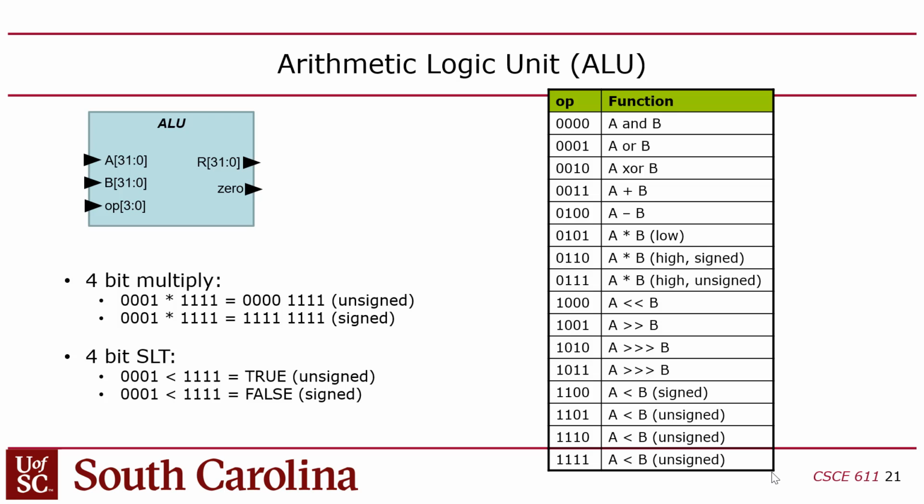Okay, so then there's the ALU. This is a combinational logic circuit. We're going to give this to you as well. This thing performs, I think, 13 or so operations. But the operations it performs are based on the opcode, which is 4 bits, so there's 16 different opcodes. Now, by the way, this is not the opcode from the instruction. This is just a generic term, opcode. It's a 4-bit signal you give to the ALU that tells it what to do. There's only 13 things it can do, but yet there's 16 different opcodes.